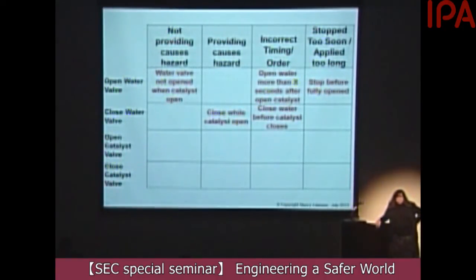So here's the answer I got. Not closing the water valve, again, wastes water, but it doesn't cause overheating. Closing it while the catalyst is open could cause overheating. Closing the water valve before the catalyst valve closes could cause overheating. Stop too soon, doesn't matter.